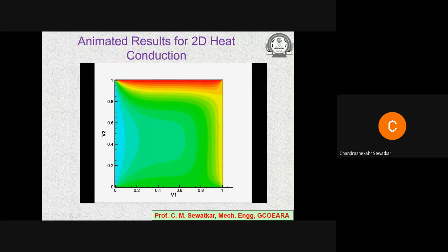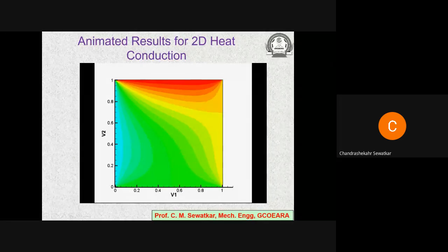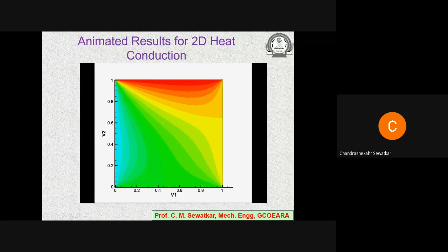Are you able to see the movie now? You can see my temperature contours are changing. So it is passing through a transient process, transient heat transfer. But now you can see once the steady state has been reached, the shape and bands of the color remain constant with respect to time. It's still transient, it's still going through unsteadiness. But now, see, now it has almost become a steady state. So these contours are now the steady state flooded contours.